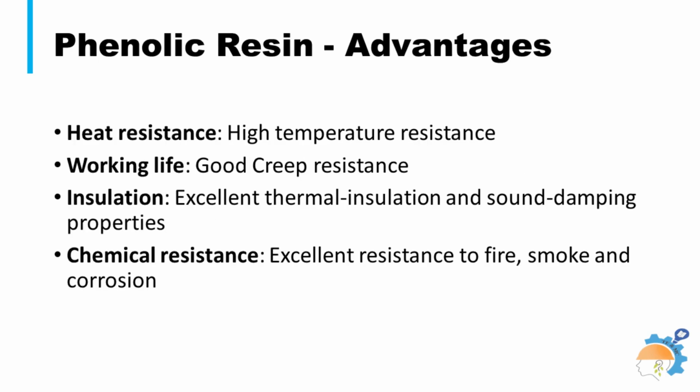Phenolic resins excel in heat, fire, and chemical resistance, offering excellent electrical insulation, durability, and machinability, making them great for high temperature and safety uses. However, these are often brittle, can be heavier, may have higher initial costs, and pose health concerns with unreacted phenol and formaldehyde, limiting aesthetic appeal, which is often solved with fillers. The best processes for producing parts with this material are open molding and resin transfer molding.